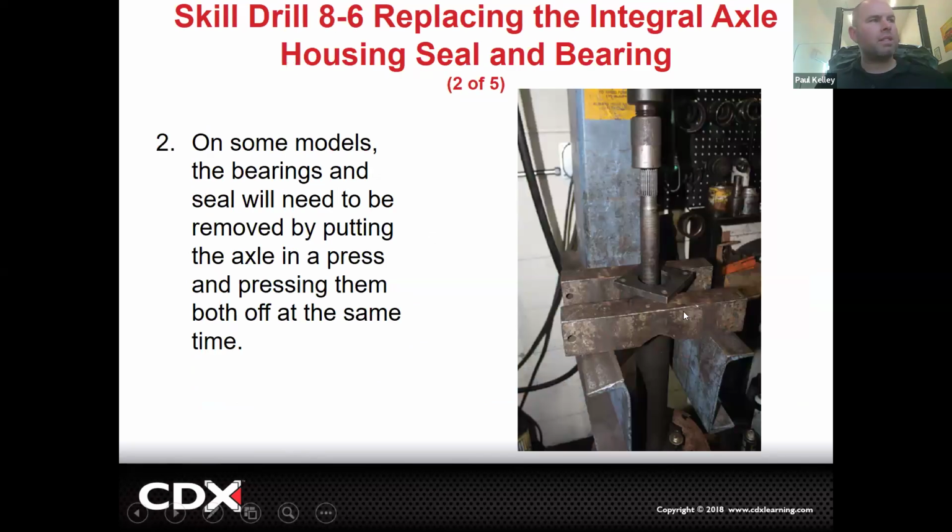If you wanted to replace that bearing, you need something like this. You need the press, and it needs to be able to go into an adapter. The press needs to have a lot of space. So replacing those axle bearings on that 3/4 float, like out of the Tacoma or Tundra, well, really any Toyota full SUV with a solid live rear axle, you need some pretty special tooling to be able to do that axle bearing. You don't just get to pull it out with a little slide hammer and tap it in with the driver. You got to put that thing on the press.